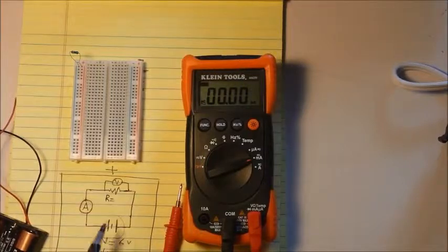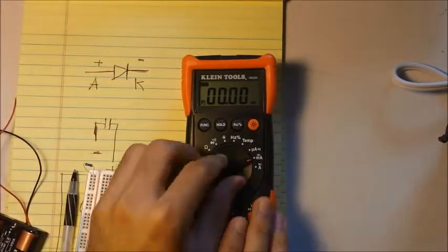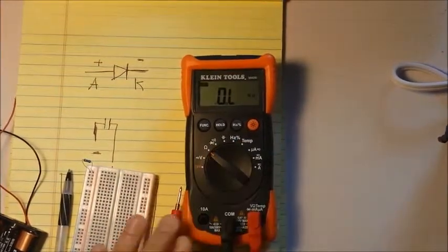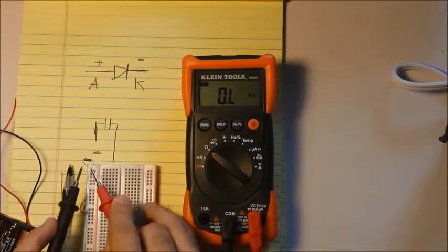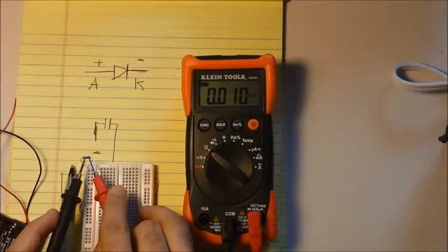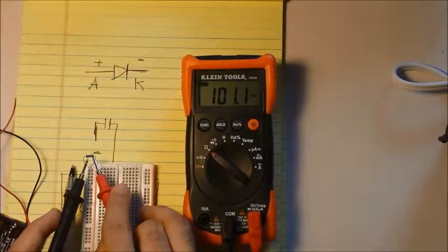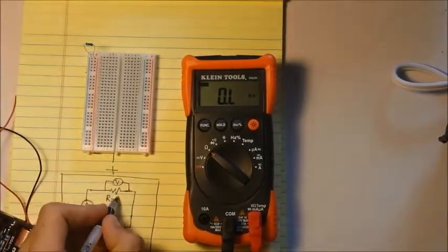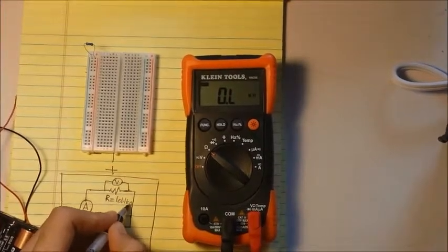Now let me measure the resistance. I choose the resistance measurement, and it's going to be 101.1 kilo ohm. So I will write down here 101.1 kilo ohm.